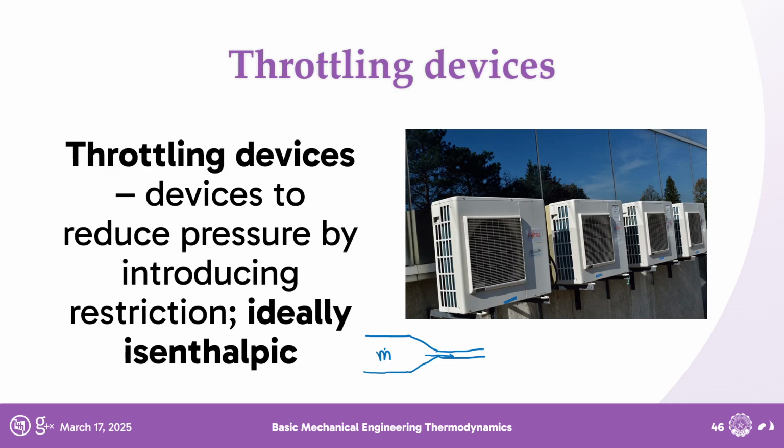That amount of logic here, unless you guys are going to take up fluid mechanics, in which case, sorry, that's the way things work, right? You can explore that more with Bernoulli's principle, right? A reduction in diameter means a reduction in pressure. But basically, this is the way the throttling devices introduce restriction, right?